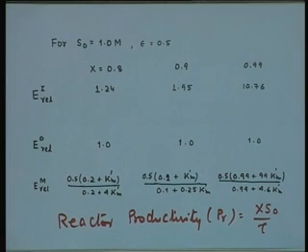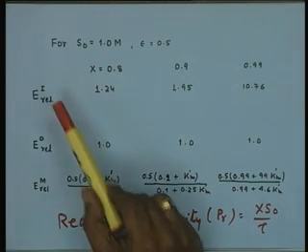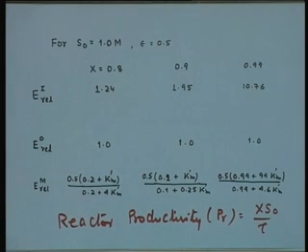Whatever we have discussed about the relative quantity of enzyme or the space time as a function of fractional conversion, the reverse behavior is true for productivity. When you increase fractional conversion, the productivity will go down, and for the first order design, the productivity of PFR will be much higher than the CSTR.